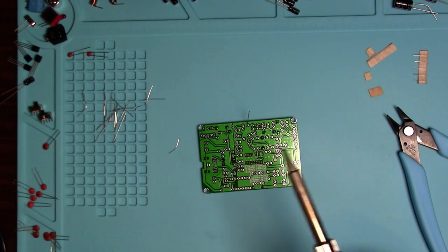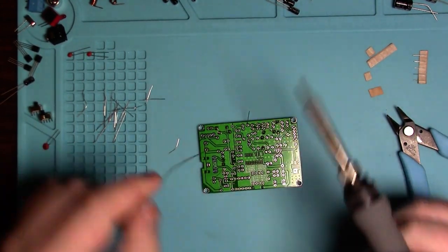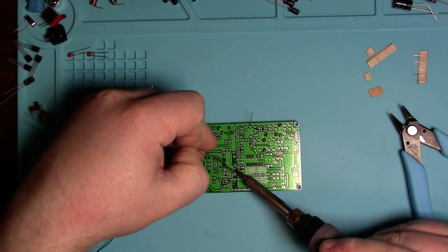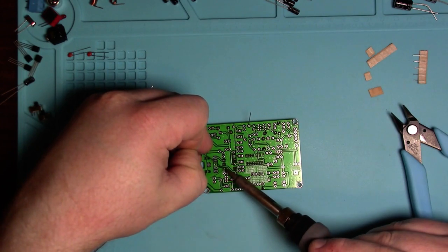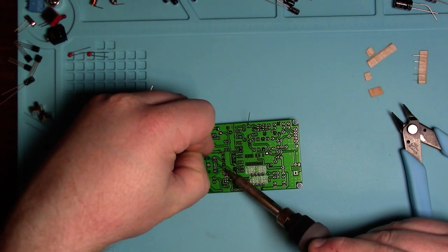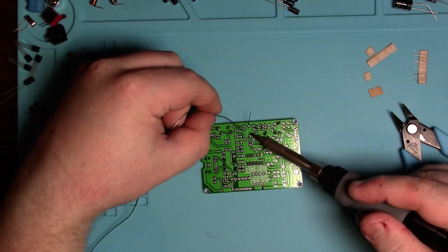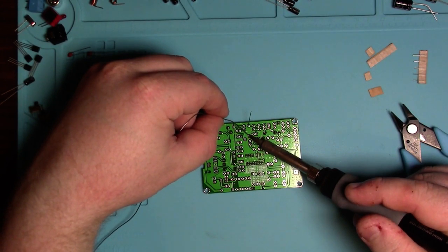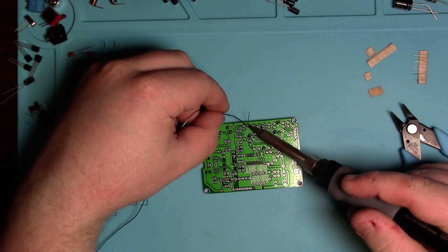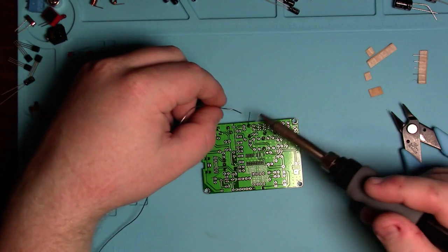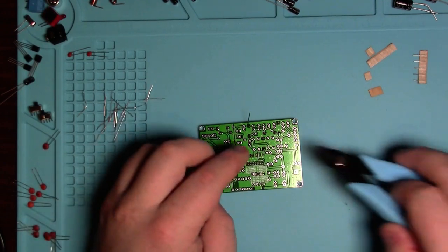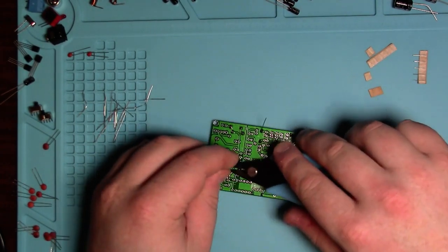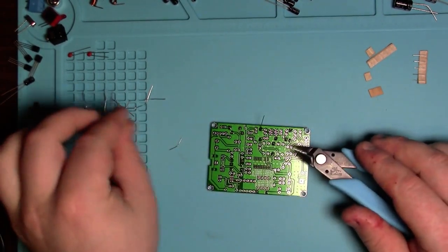So I figured out the other reason why the voltage range might be 4 to 6 volts. I think if you have 4 nickel metal hydride batteries, fully charged, they're going to be about 6 volts, and fully depleted, they're going to be about 4 volts.